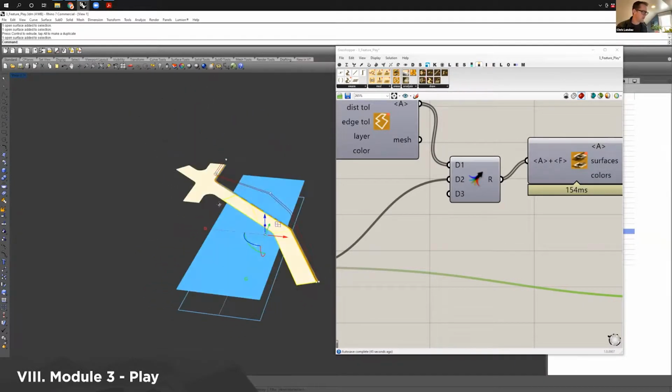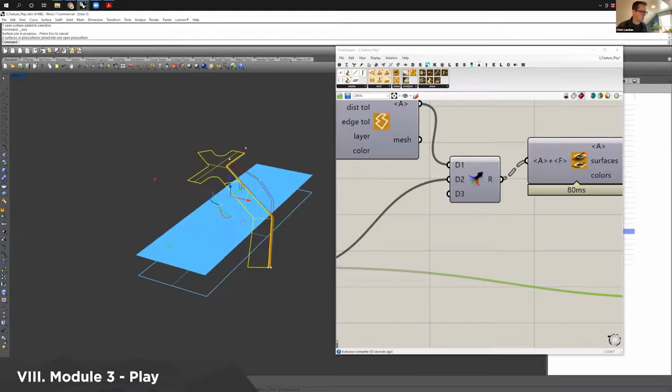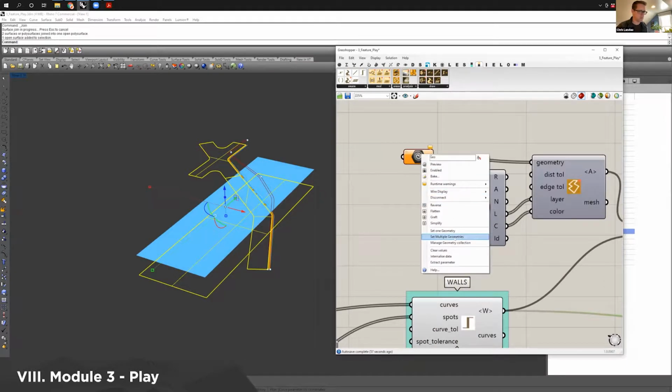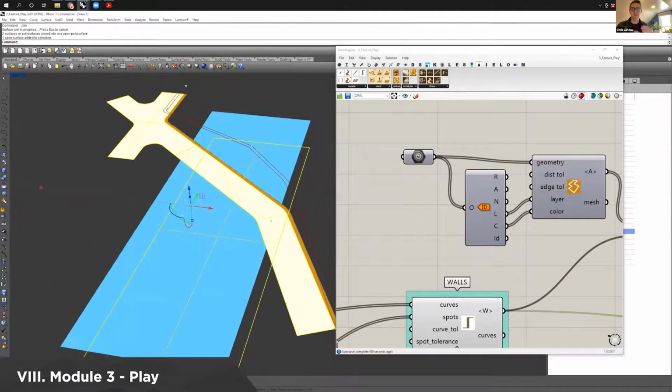The other thing that I find is happening sometimes is that whenever you have two surfaces that butt up against each other, like we're doing with these paths, if I say join, sometimes it will work. So set multiple geometries. Yeah, there we go. It sometimes gets confused with the collage tool when two things are connected like that. So it's better to just have them be one shape. And so now it works.